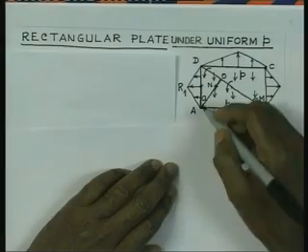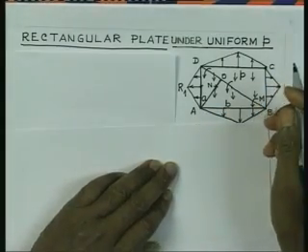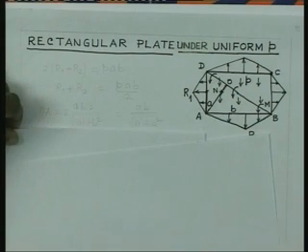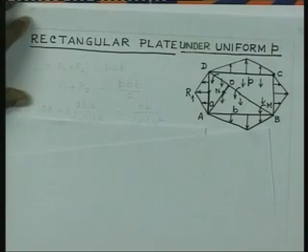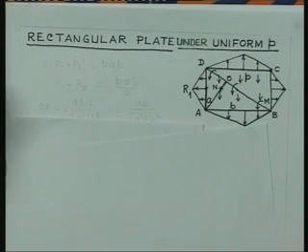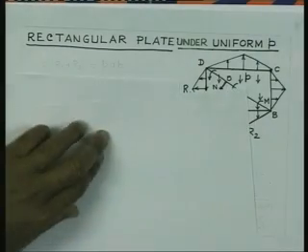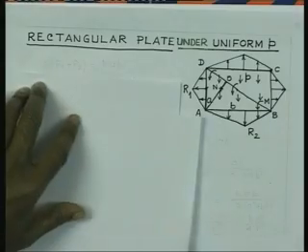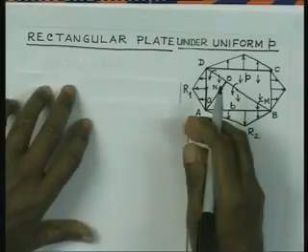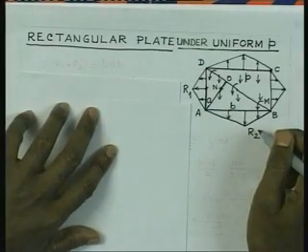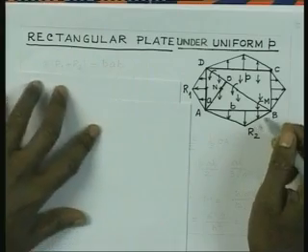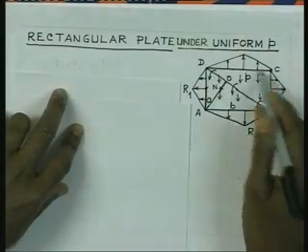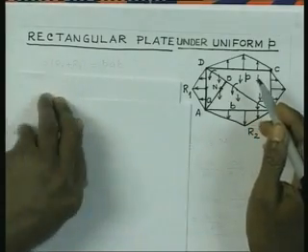Now, let us consider that this OA is the height, which can be represented. We can also calculate that; we need not actually write it explicitly. So, let us first of all write the force equilibrium. Considering the force equilibrium herein, twice R1 plus twice R2 must be equal to the external loading. So, that is the equilibrium of the whole plate.